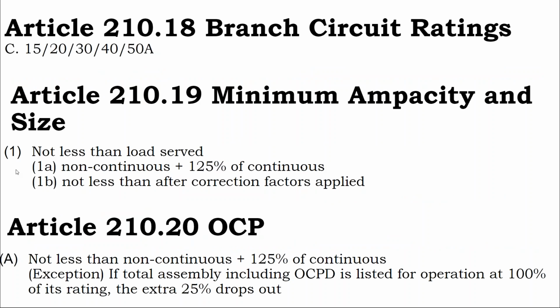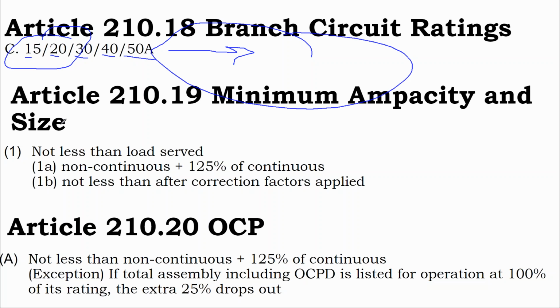I think more basically with breakers, we can learn a lot about sizing by just noting the sizes that breakers come in. We have smaller breaker groupings, but then as the breaker sizes get larger, this grouping starts to separate. And so when we're linking the breaker size to our circuits, we have to do a couple of things. One, we have to look at the ampacity of the load, and then we have to apply some safety factors, and then that's the size of the wire, and then we have to look at the size of the breaker.